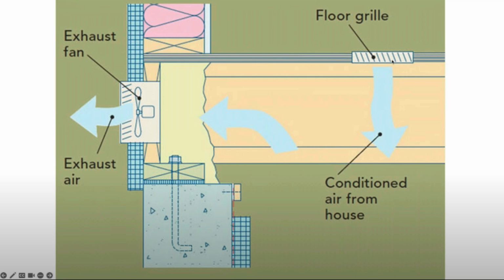We typically don't want to create that type of negative pressure. This is especially true in hot, humid climates where we commonly see crawl spaces. When you come across these types of homes and check the RH levels in the spring, summer, or fall, you will likely find high RH levels.